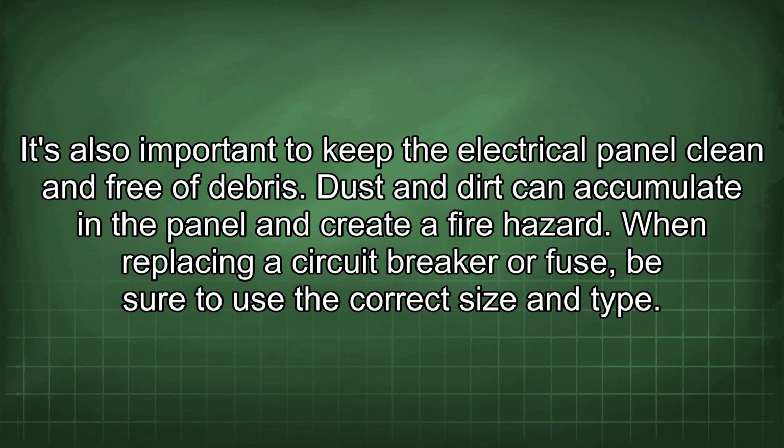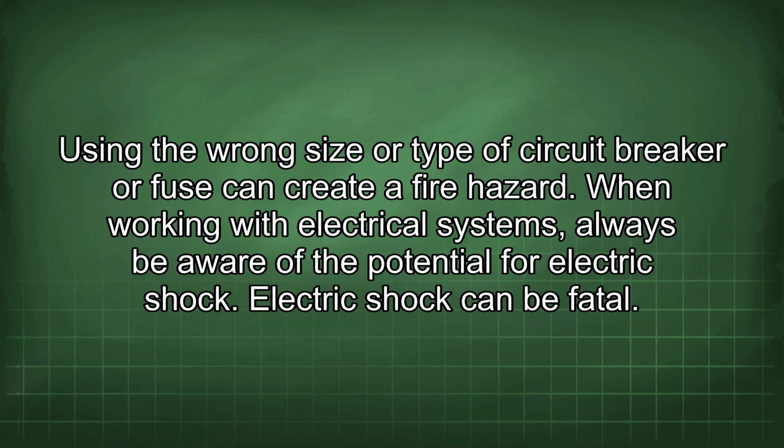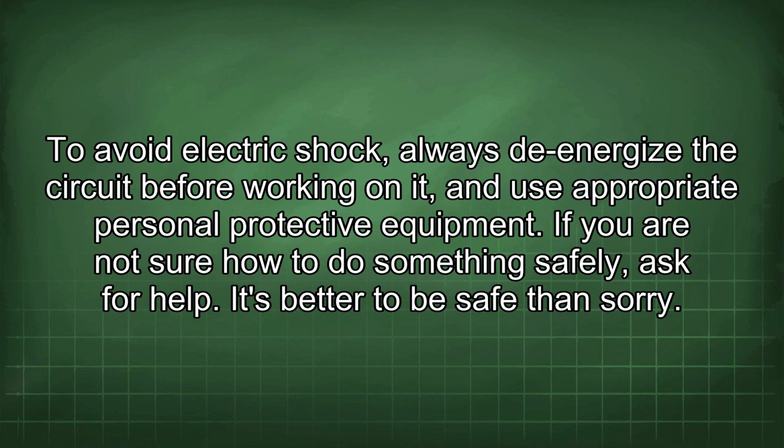When replacing a circuit breaker or fuse, be sure to use the correct size and type. Using the wrong size or type of circuit breaker or fuse can create a fire hazard. When working with electrical systems, always be aware of the potential for electric shock. Electric shock can be fatal. To avoid electric shock, always de-energize the circuit before working on it and use appropriate personal protective equipment. If you are not sure how to do something safely, ask for help. It's better to be safe than sorry.